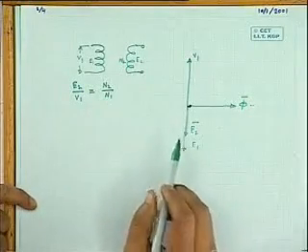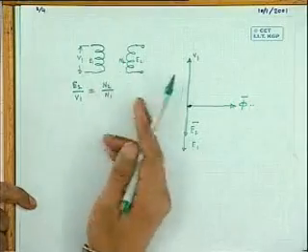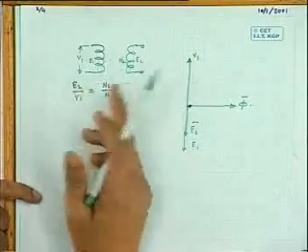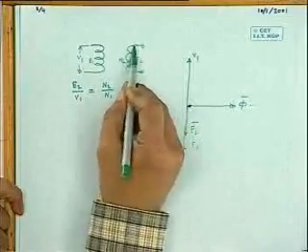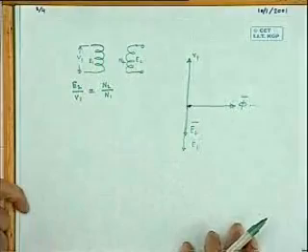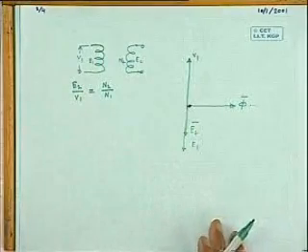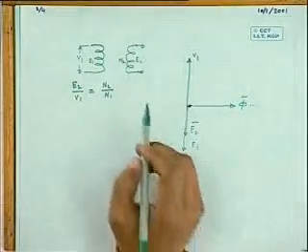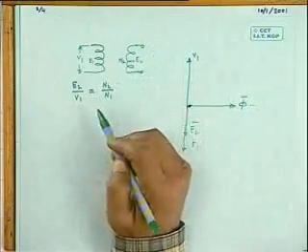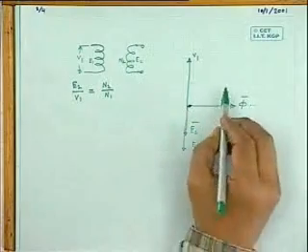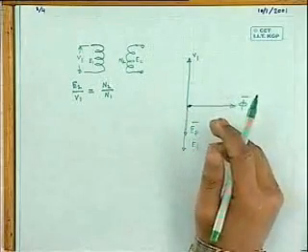Another thing, in a transformer you should note that volt per turn remains constant in the primary and secondary side. It is the voltage per turn which remains constant. So this was there, and in the secondary there is no current as nothing is connected. Now we will see what will happen if we connect a load across the secondary coil of the transformer. So under no load condition, this is the phasor diagram of an ideal transformer.